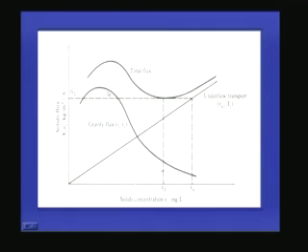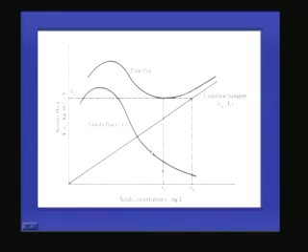Then afterwards what will happen? Though the concentration of the sludge increases, the velocity with which it is compressing will be decreasing. The reason is the sludge is so thick that it is not able to compress much more. So the velocity with which it is compressing or settling will be very, very low. Naturally the product of Vi and Xi is coming down, that is why this portion, and finally it becomes almost asymptotic like this.